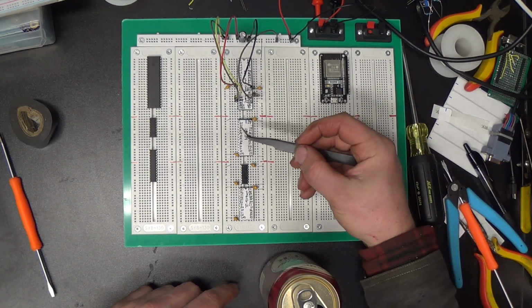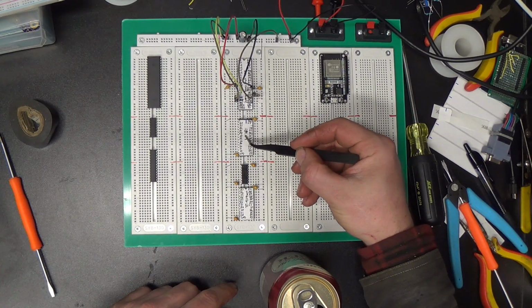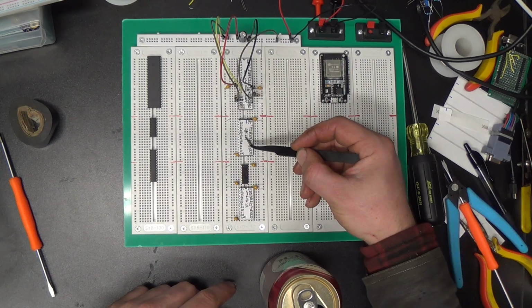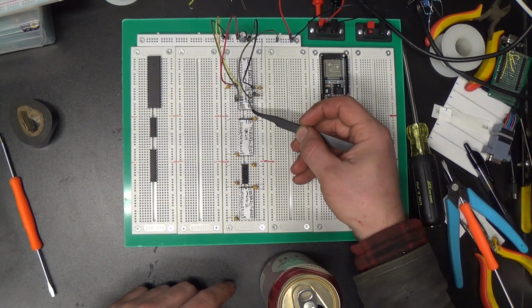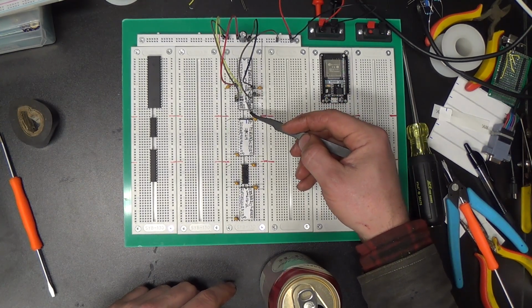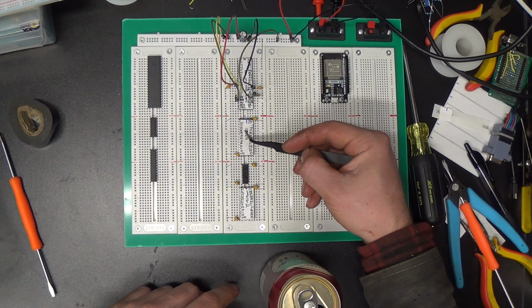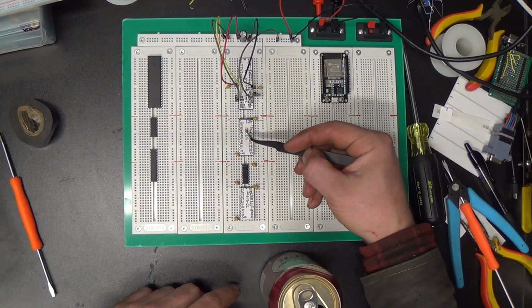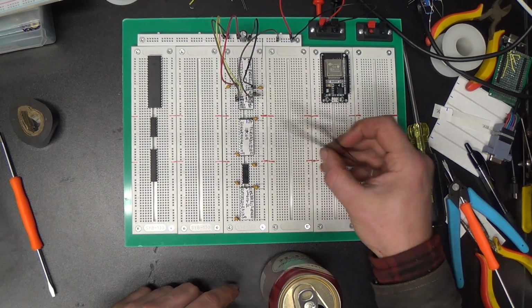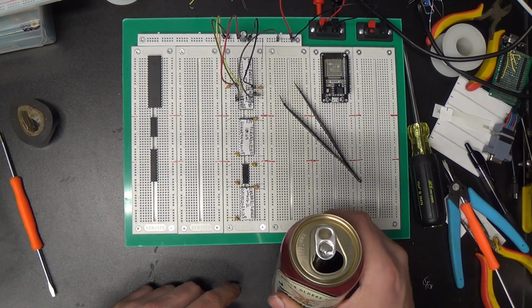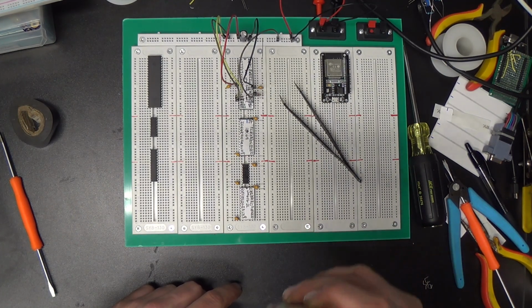So, obviously that means that we need to put this 8K ROM in the bottom of the Z80's memory map. That would be from 0 to what? 1FFF, I think? Yes, I think so. I may not be able to do hexadecimal math in my head right now for various reasons.